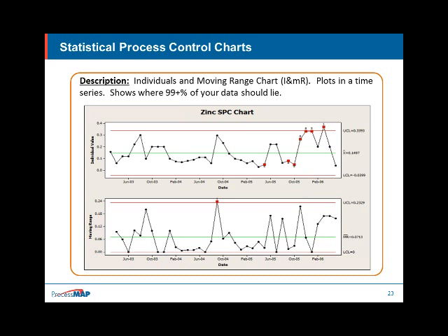You start to see these red dots here. These indicate that there's special cause variation going on here. What this means is that there's something happening in your process that isn't right, okay? That's running out, is starting to run abnormal, and there's a cause for that running abnormal. The issue behind this is that if you don't go out and understand your process to understand why these special causes happened, your process can start to run out of control on you.